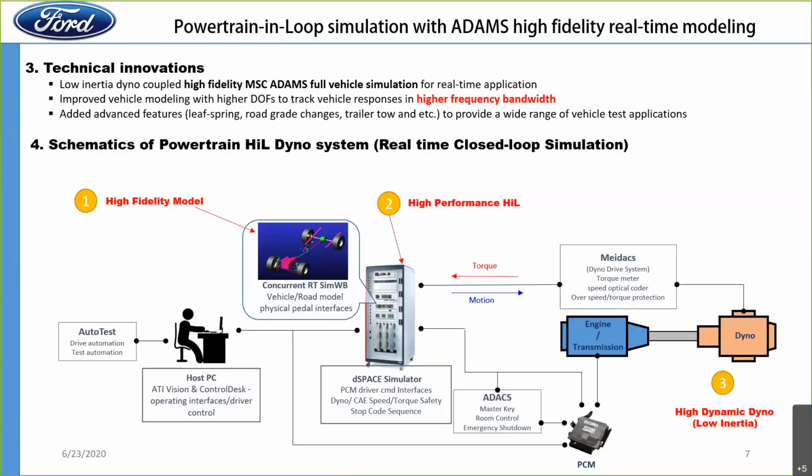I want to share the schematic of the powertrain HIL dyno system, which we made for real-time closed-loop simulation of the powertrain. First of all, we have the high fidelity Adams model running in a concurrent real-time system.